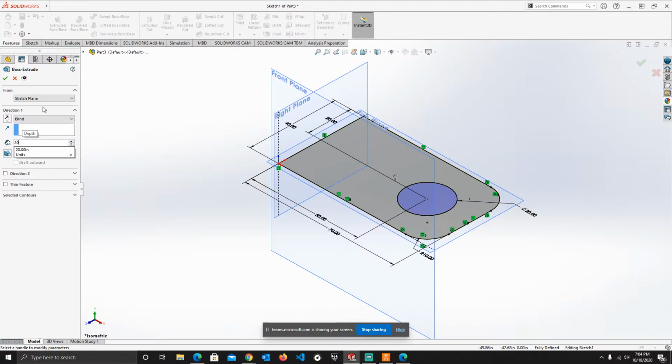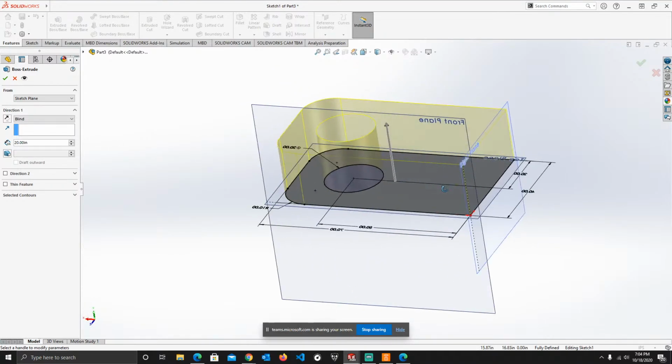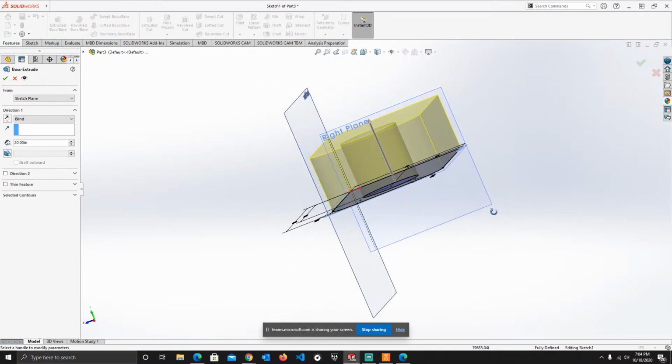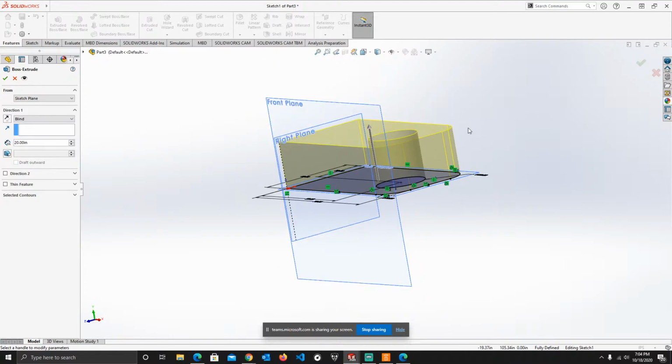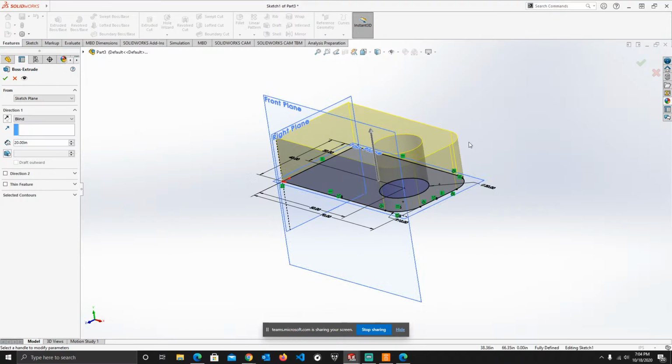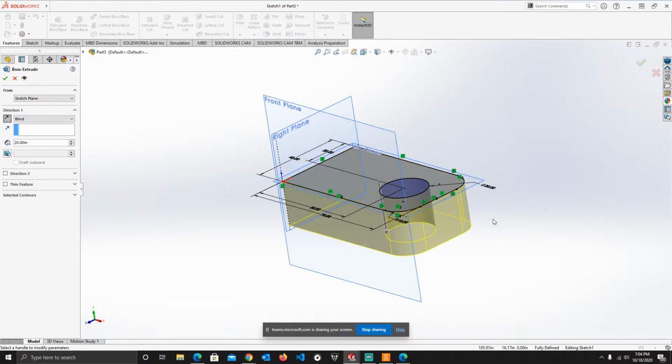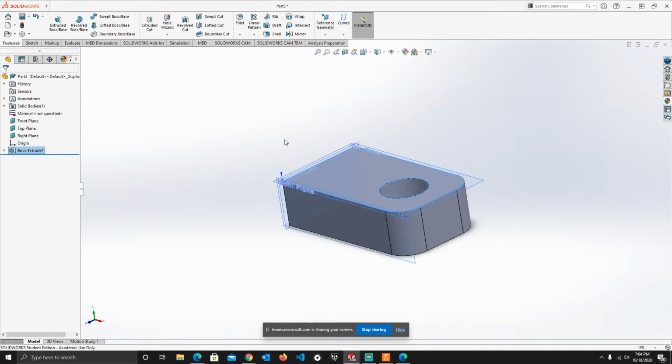And now here's another logic that comes into play. I could either extrude it 20 inches up from my surface, so my top plane, but I wouldn't want to do that because I could build on top of this figure, but usually I'd like to build on top of my reference plane. So in that case, I'm gonna change the direction of the extrusion for it to be down so that I can use my plane for some other stuff. So that's what I'm gonna do. Extrude it downwards by 20 inches. Now we have a nice first block.